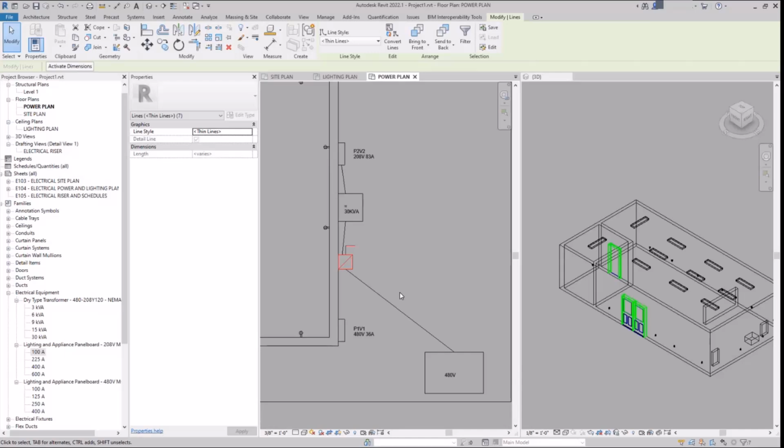It's also going to have the ground neutral bond in it, meaning this is where you would bond the neutral bus to a ground rod in the ground. Yes. Gotcha. Here is going to have the same thing, but designated as service entrance. Generally, that falls under that concept as well. Like, hey, give me the bond here.